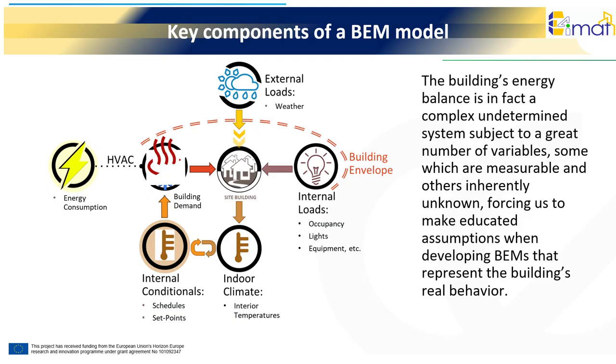These factors can be of external nature, like those generated by the weather, or internal, caused by occupancy, lighting, equipment, or other loads. The impact that these stresses cause on the building's heat dynamics is constrained by the building's envelope construction and mitigated by the internal comfort conditions established by either code regulations or the building's users. The result is the building's energy demand.